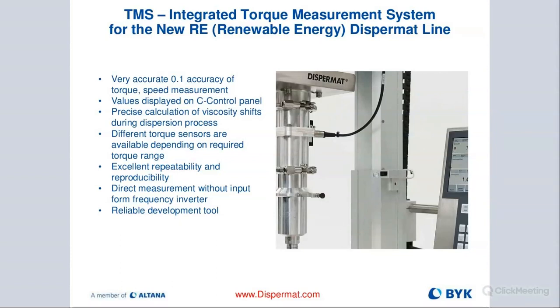So this is a whole new development, and there are also different sensors depending on the amount of torque the machine needs to put in to process different volumes of slurries. So we have extremely good repeatability and reproducibility with this system. And obviously we no longer need the data from the frequency inverter. Everything is measured directly on the shaft with that new sensor. So it's a really good, reliable development tool, and you can also integrate the same system into a pilot or manufacturing unit.